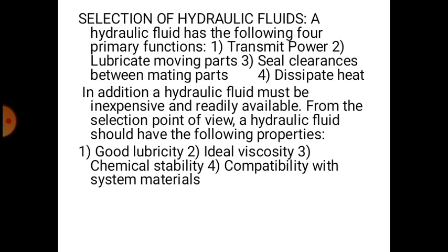Selection of hydraulic fluids. A hydraulic fluid has the following four primary functions: it is used to transmit the power, lubricate the moving parts, seal clearances between mating parts, and dissipate heat.